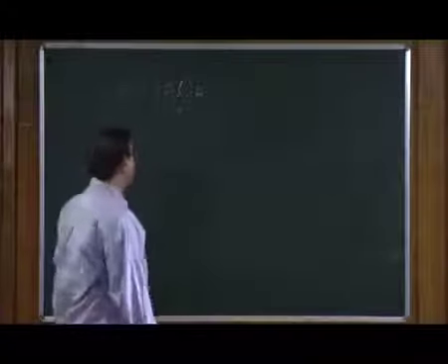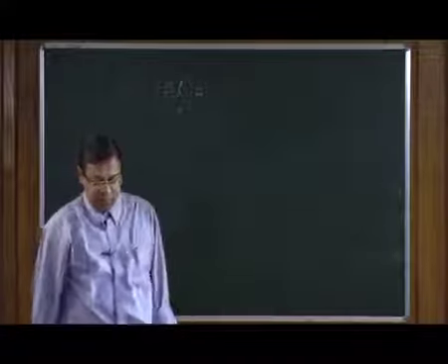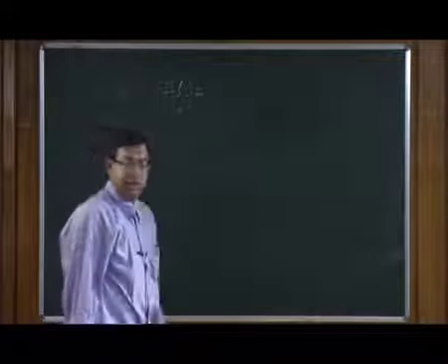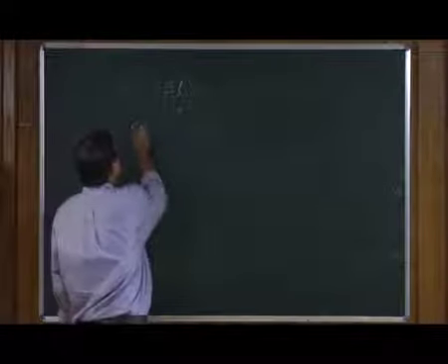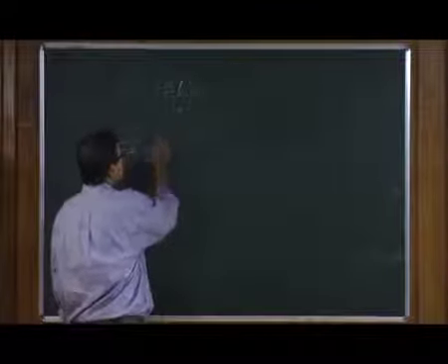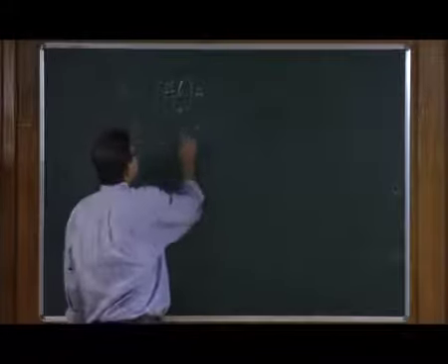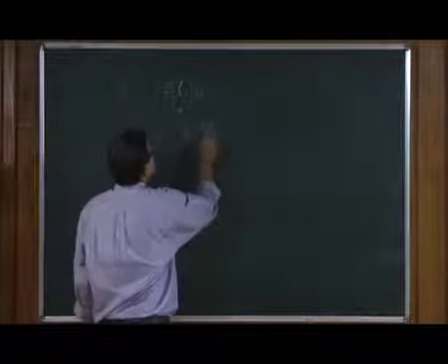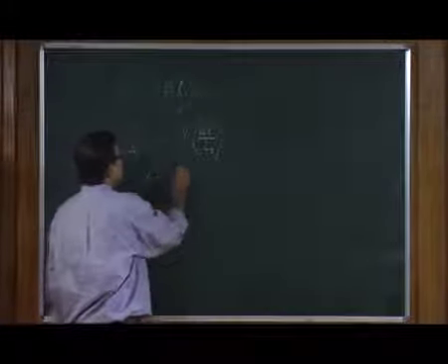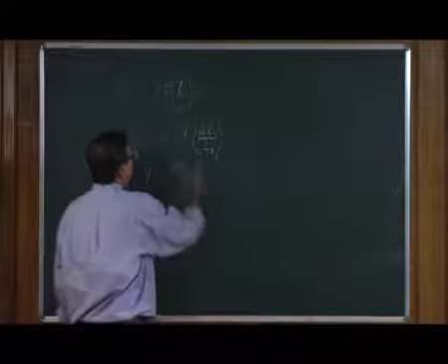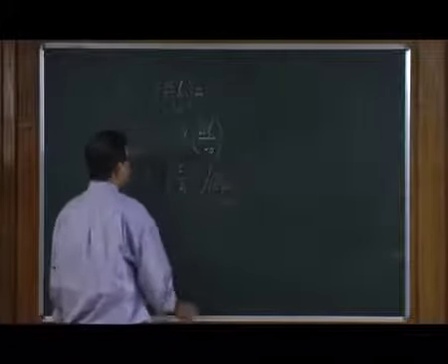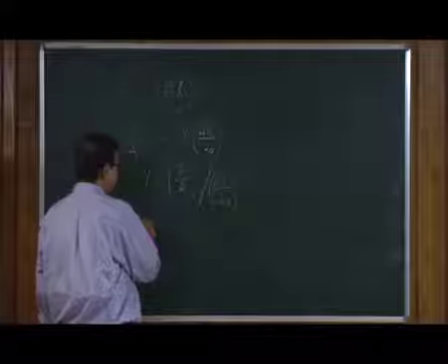So, let us just come to this discussion of tensile stress that we had briefly spoken about, but hadn't elaborated on. If I simply divide both sides by A, the area of cross section of the material, the rod in our case, then Y can simply be written as F over A divided by delta L over L0, and as we have said, Y is called the Young's modulus.